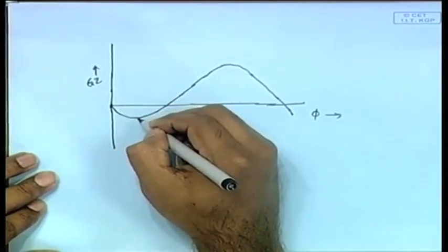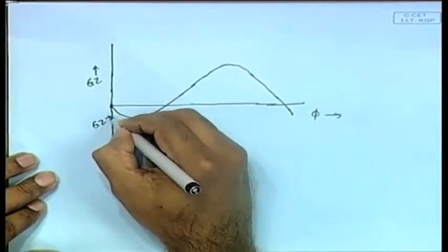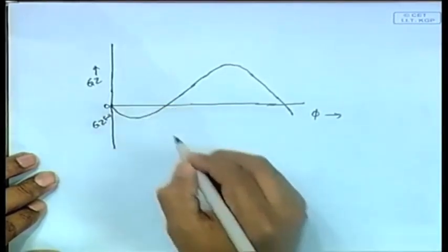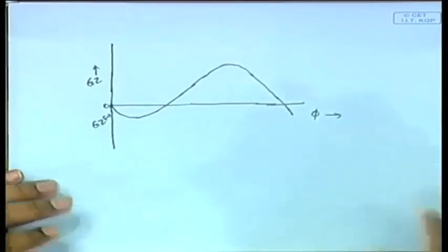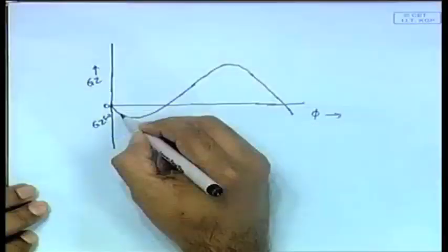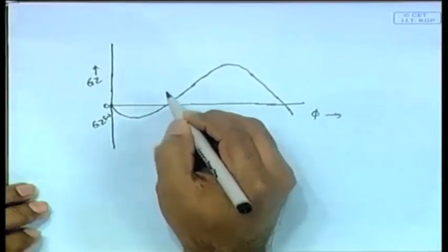If the curve is going down, what does it mean? It means that GZ is negative, obviously, and that means the righting arm is negative. What does it mean? It is not righting the ship, it is trying to heel it, actually trying to capsize it, going the other way around. So in any of these regions where GZ is negative, the ship is initially upright.